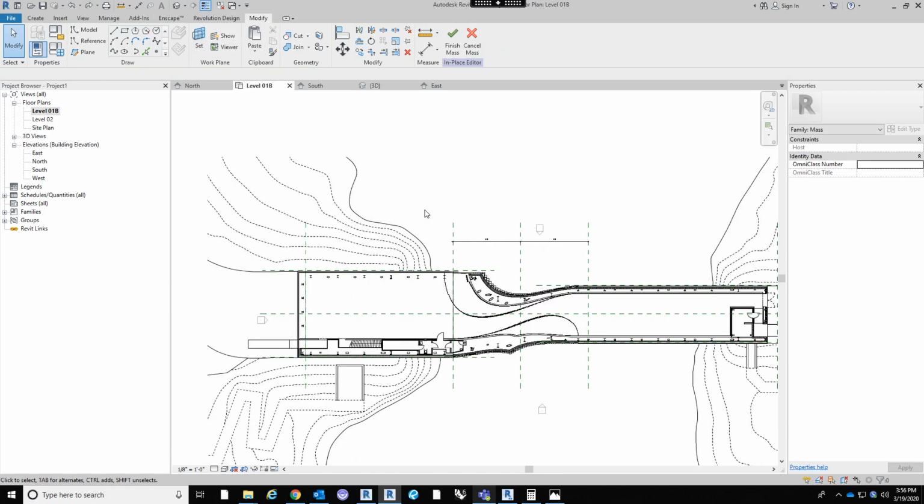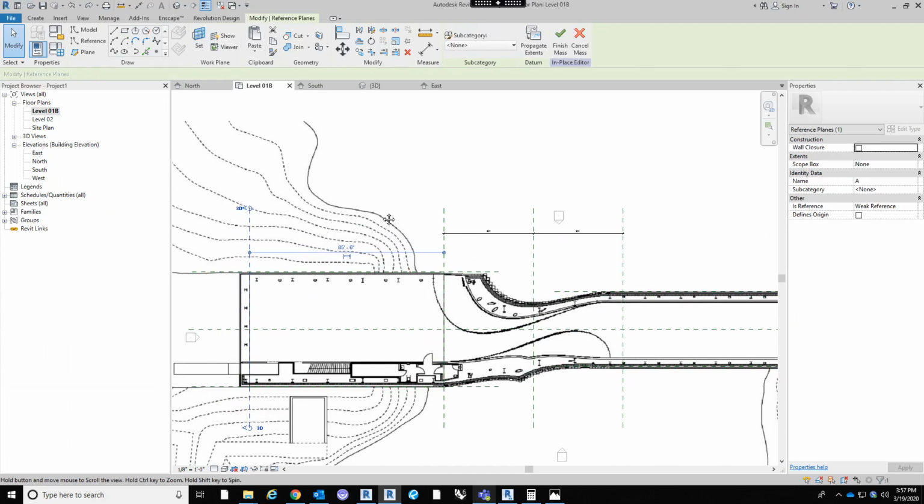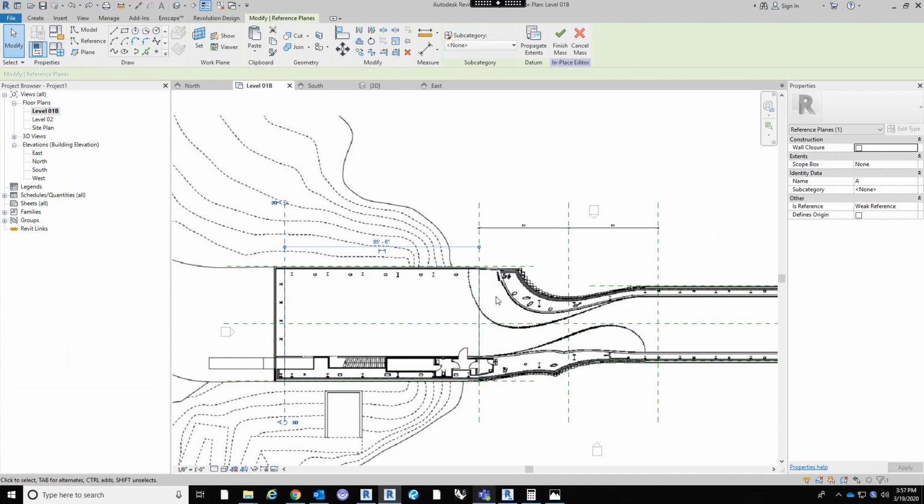Okay, so I figured it out. Essentially, instead of trying to do more profiles in the center and control the rotation that way, actually creating more profile lines in the straight sections is much easier, and it gives you a nice gradual rotation in the center. So I tried one division, and it still was giving me some weird, funky form in the far right. So I'm going to create two.